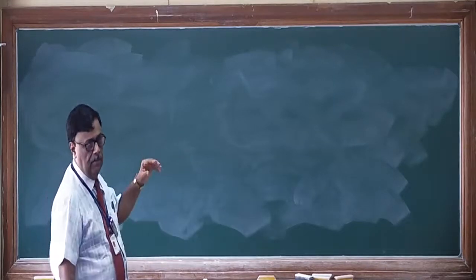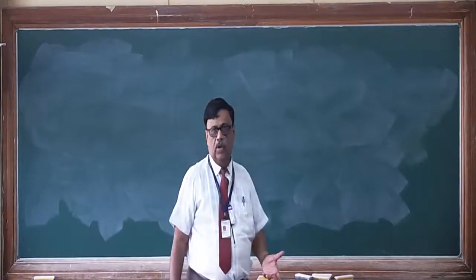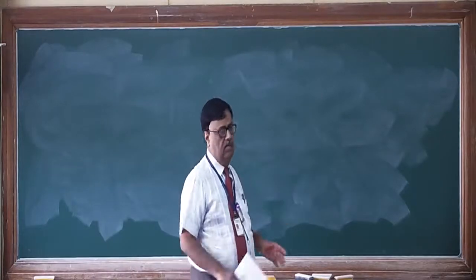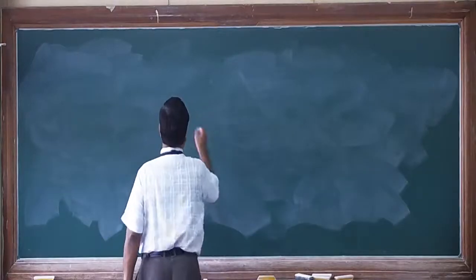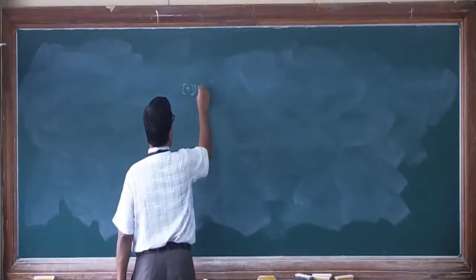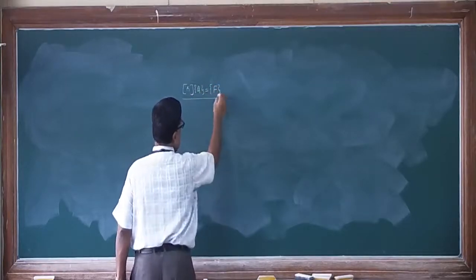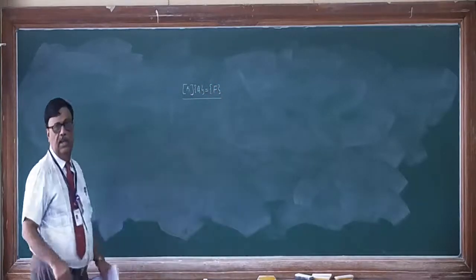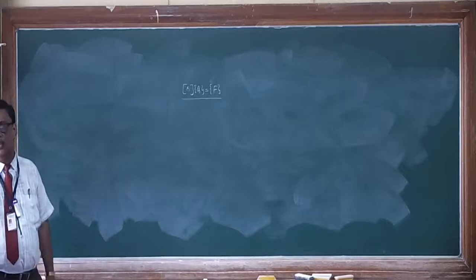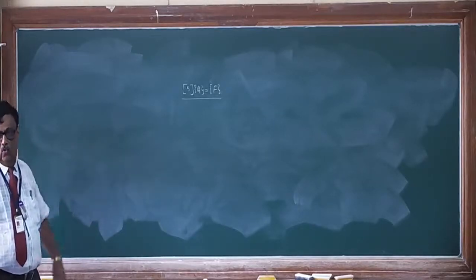And then when you club up all the influence of body force, traction and the point loads into the global vector, then the very famous finite element equation, KQ is equal to F, will be formed, and with appropriate boundary conditions and all that, you can finally reduce this and get all the nodal displacements of the entire structure, Q1, Q2, Q3 and so on.